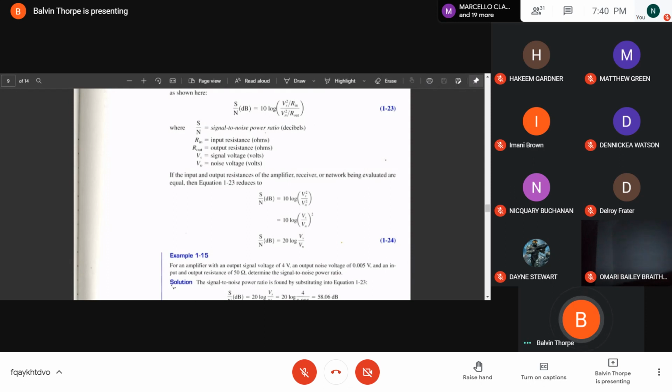Why are you using that? Because that has to pan out in terms of link budget to see whether or not the signal will survive from your transmitter through your system to your receiver and still has high enough power level at the receiver, based on the receiving equipment, to actually receive the signal in a manner that is usable. So in a nutshell, that's kind of what you're expected to do.